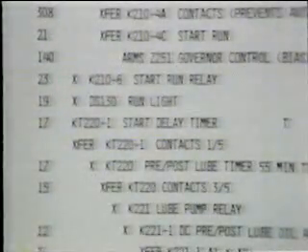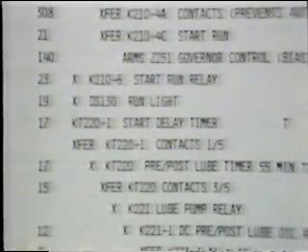The logic chart is read down the page line by line. The various events that occur can be described as either a main event or a subsequent event. The two are distinguished according to their indentation. The closing of CB501 is a main event and is placed in the far left-hand column. After CB501 is closed, there are 4 subsequent events that occur as a result of CB501 being closed. The four events are indented to indicate what happens after CB501 is closed.